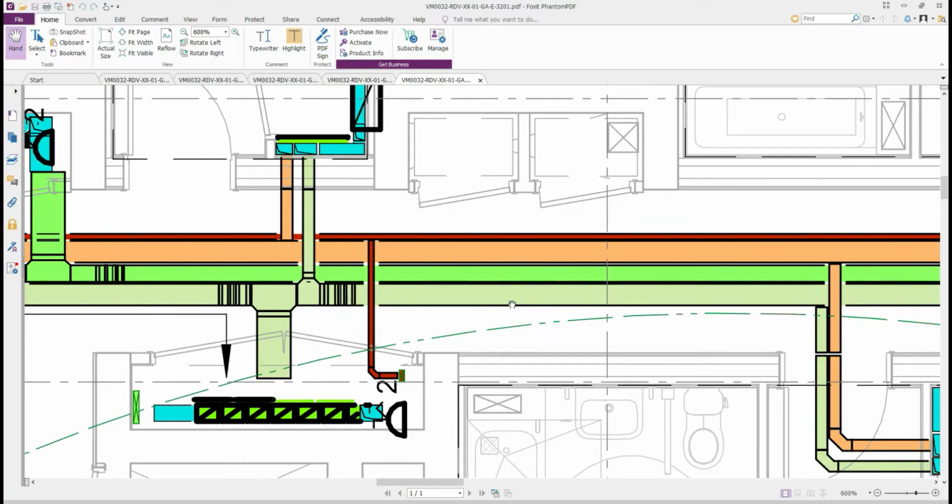I'm gonna place DNO basket 210 by 59 millimeters size, and gonna keep it 250 millimeters away from the wall. And then LV basket 110 by 59 millimeters size, and keep it 50 millimeters away from the DNO basket. And then 50 by 50 fire alarm tray, and keep it 200 millimeters away from the LV basket to allow some space for lighting. And finally 310 by 59 millimeters ELV basket, and keep it 50 millimeters away from the